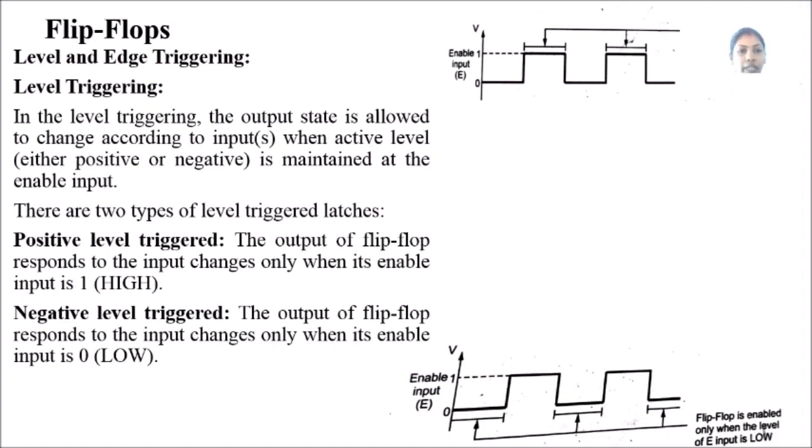When coming to negative level triggering, the output of the flip-flop responds to the input changes only when the enable input is 0, that is low. So that is called negative level triggering.